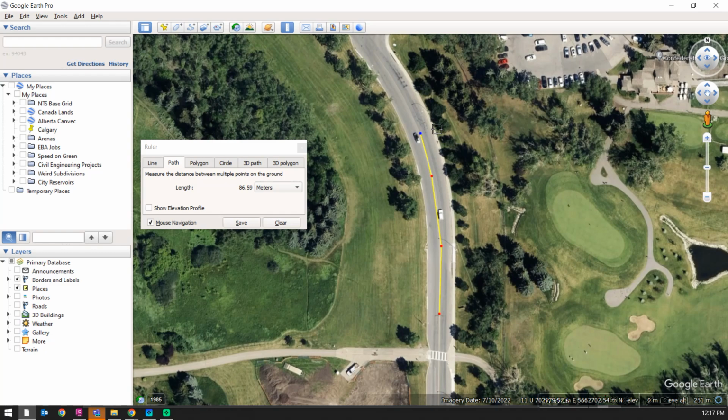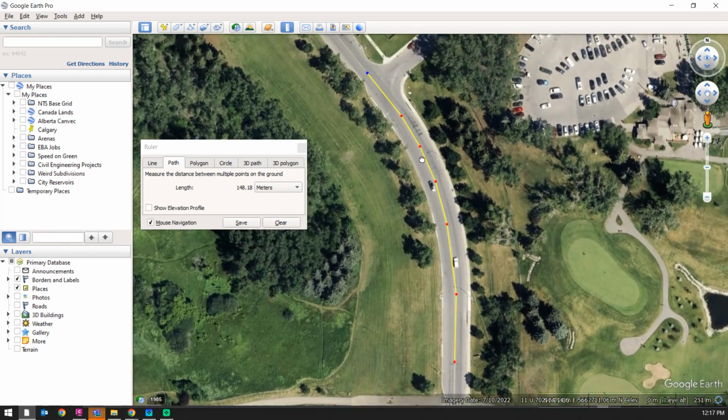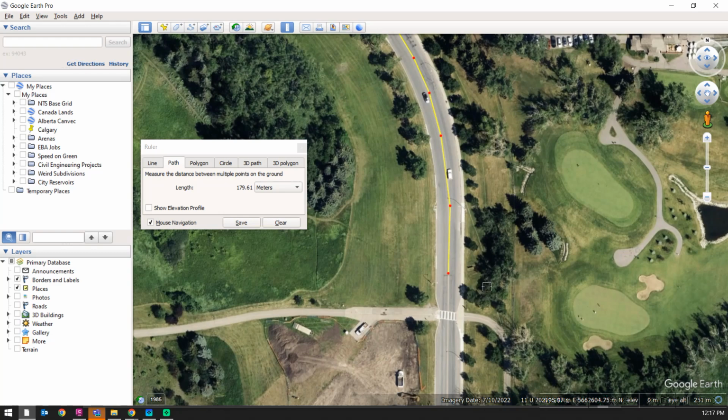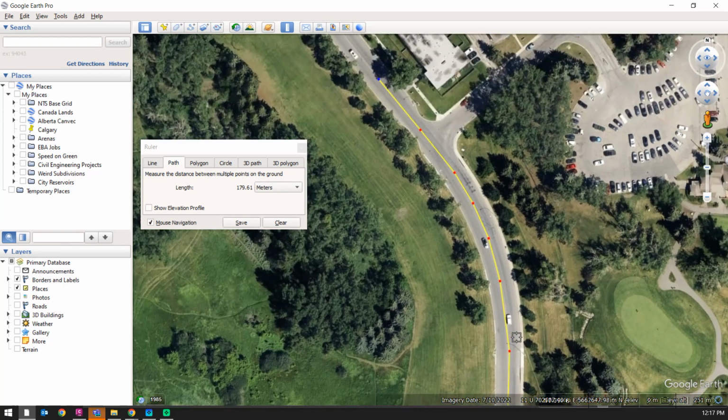In theory, they're going to place a pipe in, rubber gasket, bend and angle it a little bit. So as you go around the corner, are we going to add another manhole in Civil 3D? Right, for this section, do we need to add any additional manholes? No, because we're less than the 185 meters. So we'll have a manhole down here with a tangent pipe. In Civil 3D, we'll have one pipe, then we will have a long curved pipe for the curve, and then another tangent pipe.